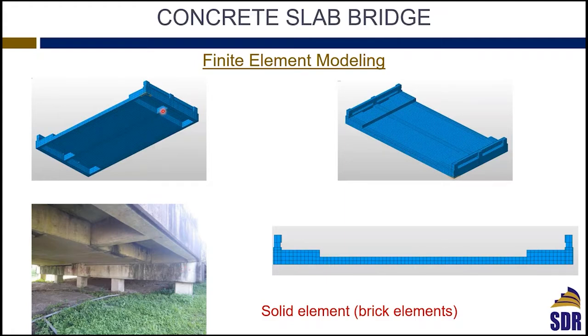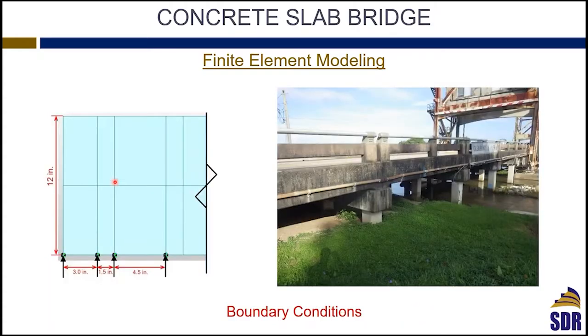So you can see the model that we are modeling the exact geometry of the bridge using solid elements. Even the barriers have to be modeled since they were cast in place barriers. So it is an integral part of the bridge. It's not only the slab, but the barriers, the diaphragms, and everything. So this model using solid elements has to be matching, I wouldn't say exactly, but as close as possible to the actual geometry of the bridge.